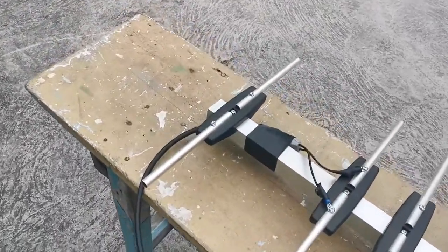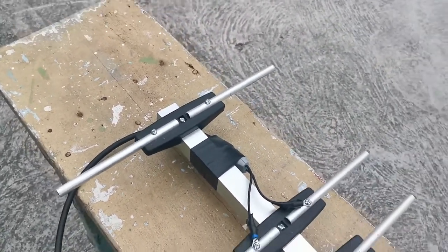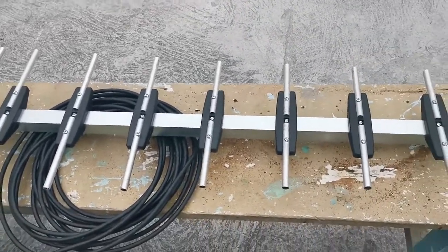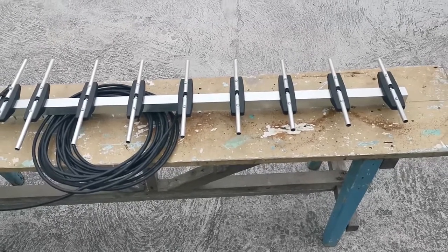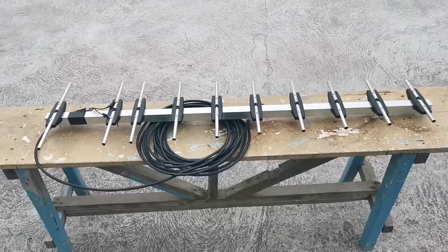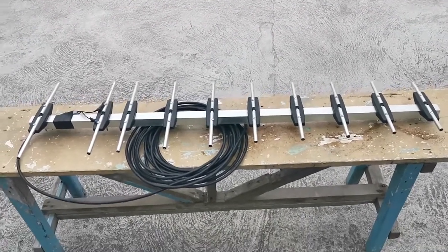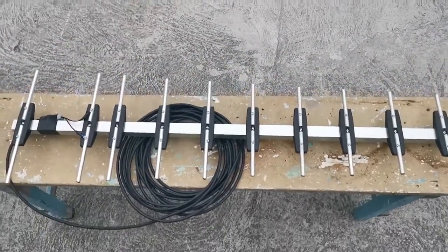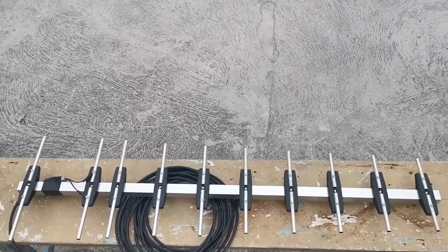The parasitic element is composed of a reflector and directors. A reflector is located at the back of the feed point and is used to bounce the radiation back into the dipole, while the directors guide the radiation in the direction of the dipole. The gain in Yagi Uda is determined by several factors, which are the number of directors, element spacings, and the length of elements. However, the most critical factor is the number of directors.